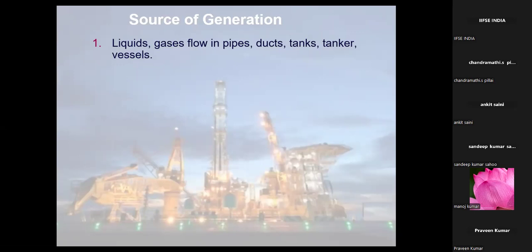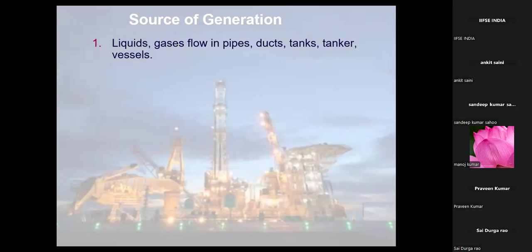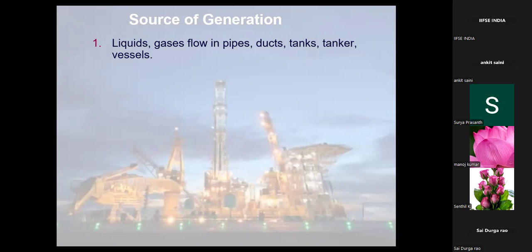You got my question? If there is a truck with raw material coming to your premises, how would you unload that? As a safety officer, what precautions would you take for the tanker to unload? Earthing. Earthing of what? Vehicle. Yes sir, earthing of the vehicle, and while entering, there is a spark arrestor.